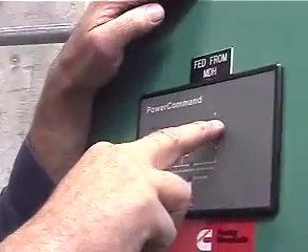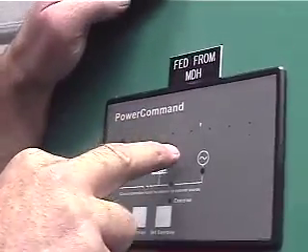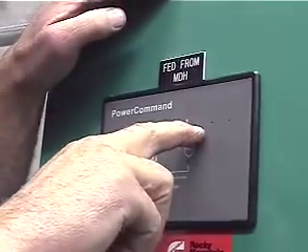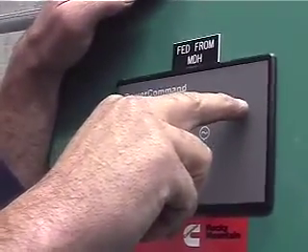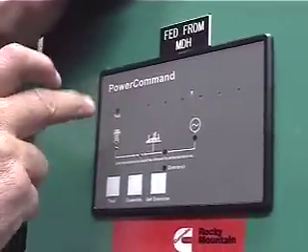Then you go to the front here and your lights are going to go red. You're going to have 5 on the left and 3 on the right. You go through test, and it's got a code in it, so if you have 1 dot come up, you're going to program time delay start, which, depending on how many seconds you want, you're going to have 1, 2, or 3 lights lit. And then you just go down through it. There'll be certain lights lit depending on what it is. That's what the little plastic chart's for, that I always leave on the doors. I don't know why Tyson didn't leave them on the door. But that's how you do it.